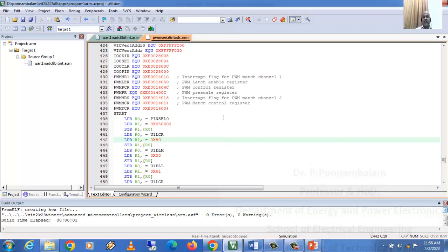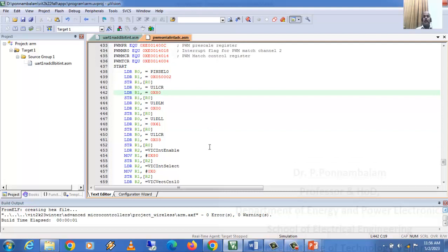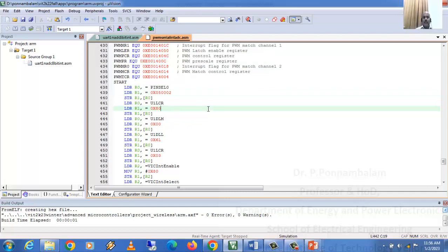In the other microcontroller, that is the remote microcontroller, we'll be receiving the digital value, and after it has been received, we'll put the value into the PWM. So the PWM's duty ratio will be decided by the digital value that is obtained from the sending end microcontroller. So in turn, that is dependent on the analog value which we are feeding into the analog to digital converter,